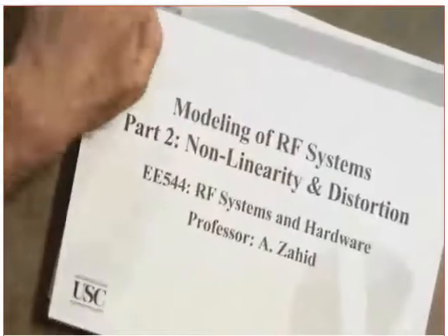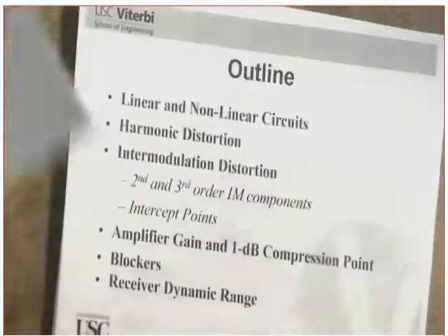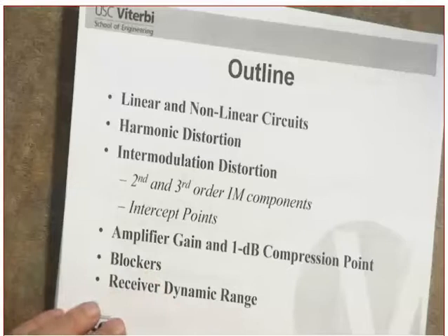Now let's get back to the analysis. So we have the nonlinearity distortion. Remember, by the way, one more time, a linear system is a system that does not create new frequency components. It can attenuate, it can amplify. Are you following me? But it cannot create new frequency components. Clear? All the devices that we are going to be looking at in the receiver are what?